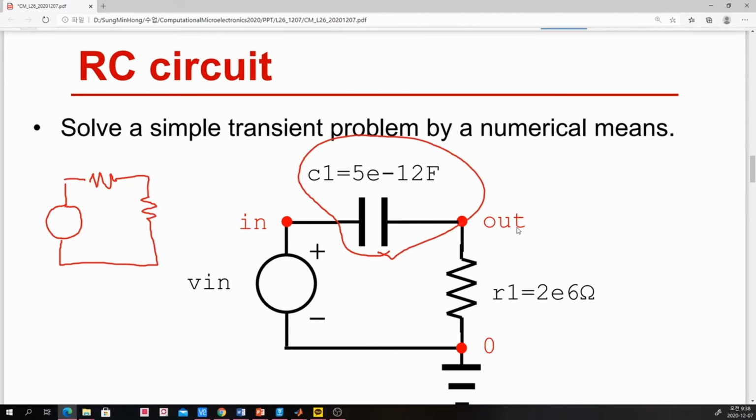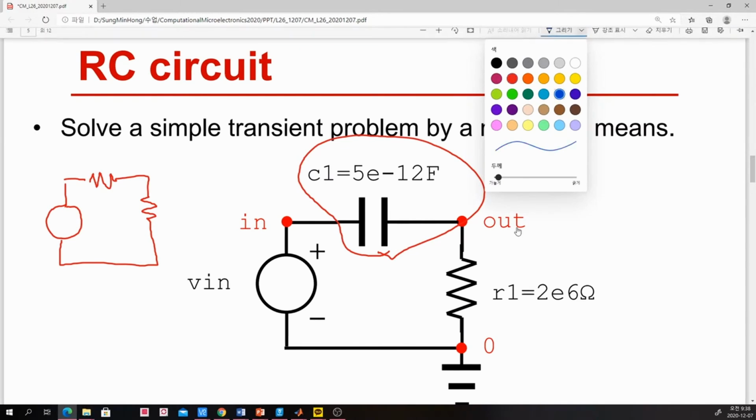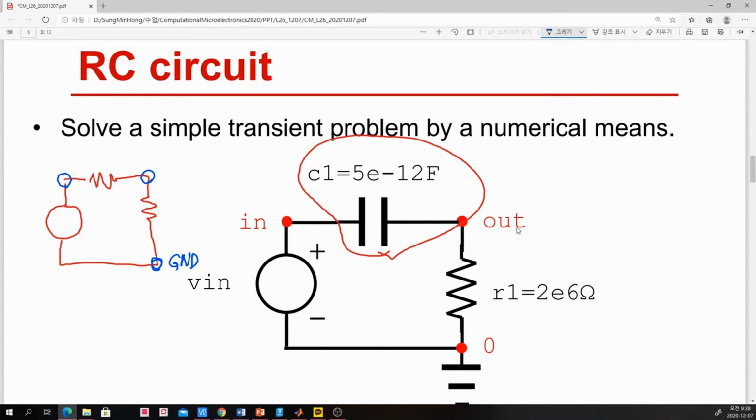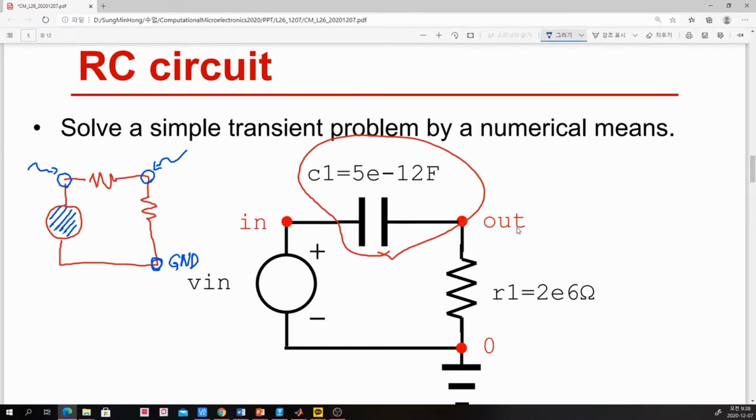In this case, of course, if we have two resistors, then we will have two non-grounded nodes. Of course, here we have a ground node, but the ground node can be omitted because this is really ground. And here and there we have two nodes. Then we can apply two KCL equations and three equations for circuit elements: voltage source, resistor, and resistor.